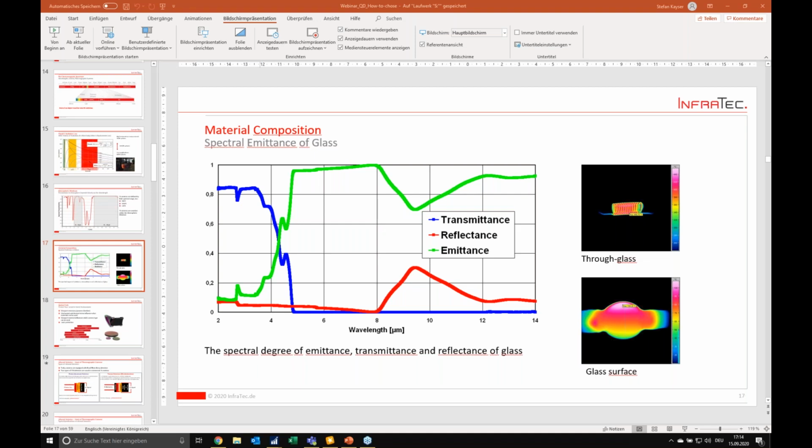So a furnace or a boiler depends on the material you're measuring, also the surface material of your objects. So it tends to be metal surfaces. Metal surfaces in general are complicated for IR cameras, because the emissivity of such an object over a wide range of the spectrum is poor.